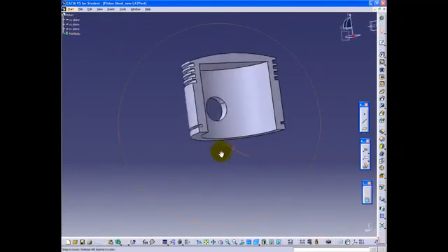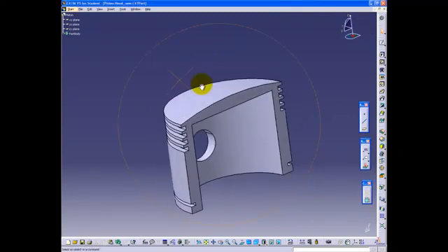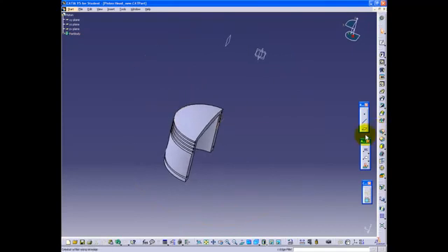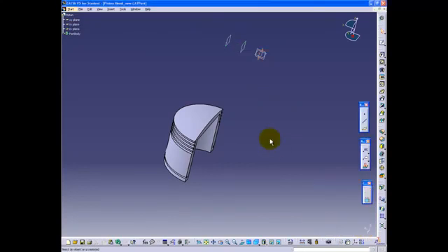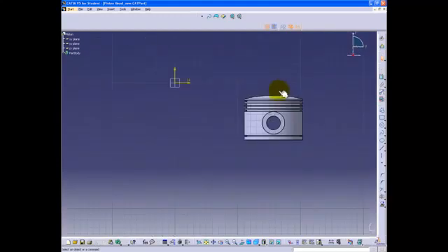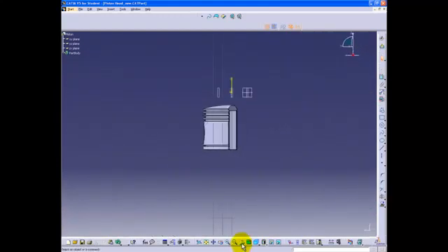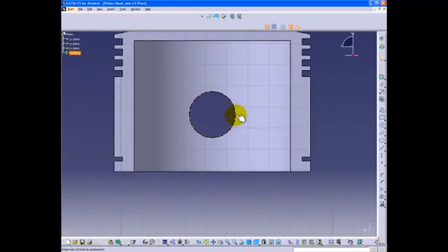At this point, we will now be ready to create the raised intersection of the piston. Now we are ready to create the inner raised circular ring. This will be done by creating a plane that is 25 millimeters away from the YZ plane. This will effectively create the base of the inner circular ring that you see if you were to turn the part.